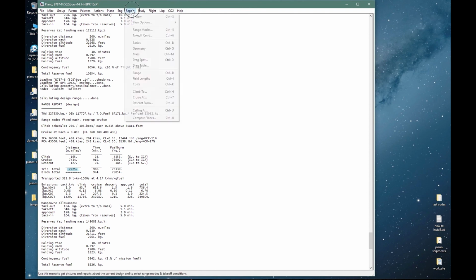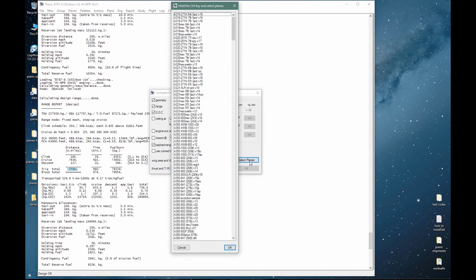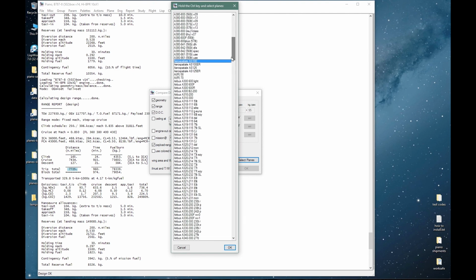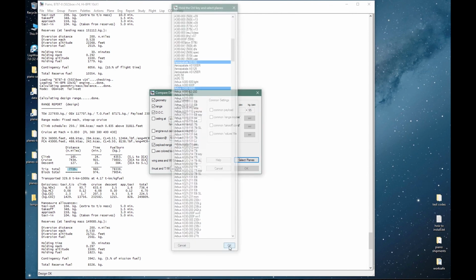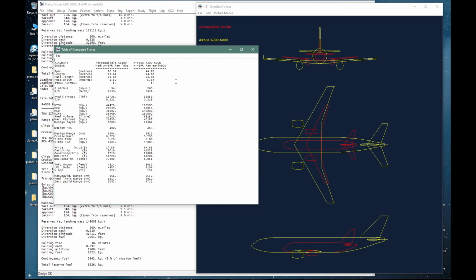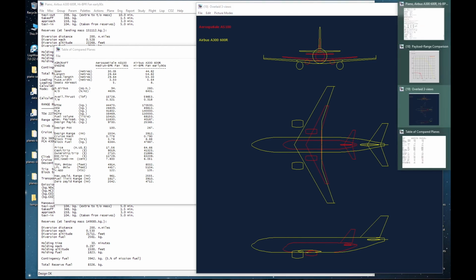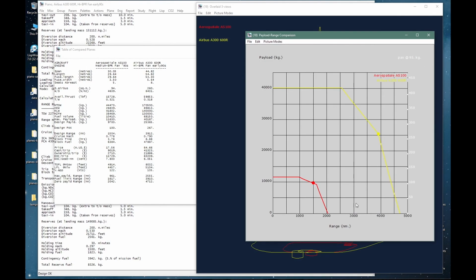Another thing you can do is side-by-side comparisons for two or more aeroplanes. You can choose the things that you want to look at, and we will look at an Airbus definition of wing area and available thrust definitions. Let me select two different aeroplanes. There is an Aerospatiale 100, an old project. Let's pick up an A300 as well. And we run them both. You get a tabulation of the basic characteristics in a comparative sense, three views with the schematics of the airplanes on top of each other, and payload range diagrams overlaid on the same picture. I will pause here and continue in the next clip.